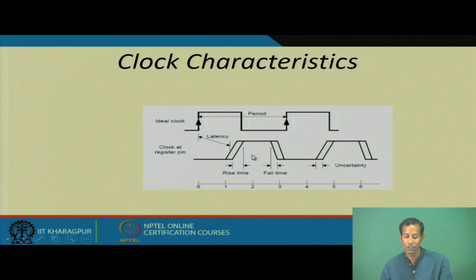And then, it is not the case that every clock edge occurs at the same time. The difference between the clock edges of different clock pulses is known as the uncertainty. So, this uncertainty value is the information about how much jitter you have in your clock. You have to set the uncertainty on the clock period, because in real time you will face this uncertainty, and this is the real clock which will work inside your chip. That is why you have to consider this uncertainty value while you are defining your clock.